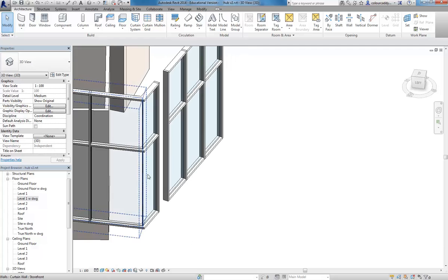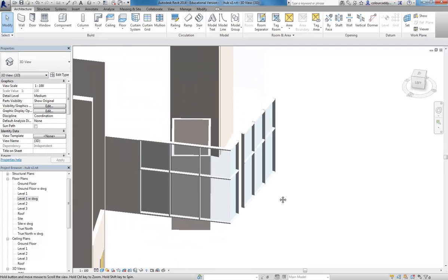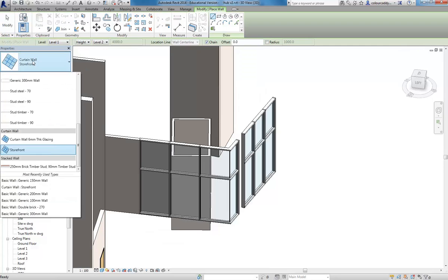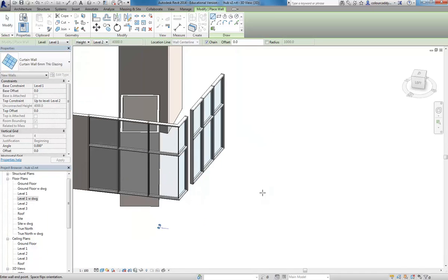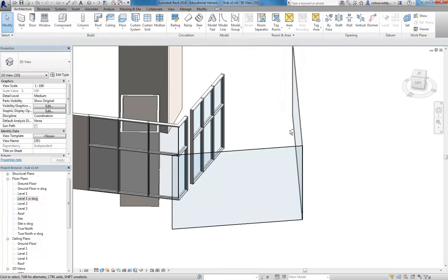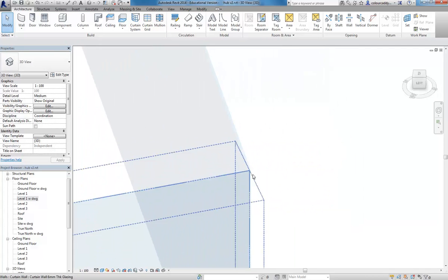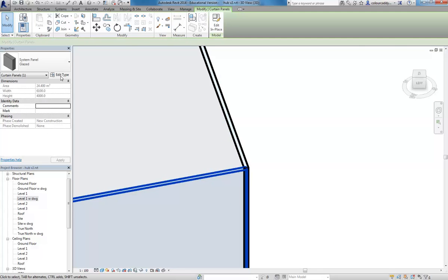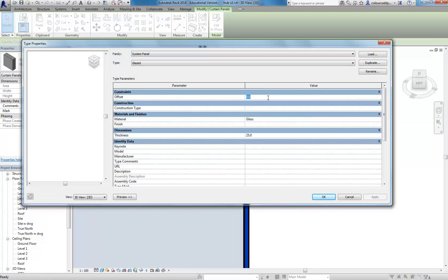So curtain walls, they're not much more difficult than regular walls. But other than the storefront wall, at first you'll only have the plain glass, which is this curtain wall 6mm thick glazing, and it's at first going to be set up the same way. Here it's joining because I've changed my panel. So if it had that offset, it'd still be...